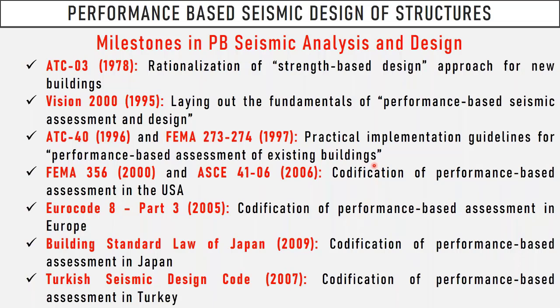As I mentioned, it started in the mid-1970s, ATC 3. It was the first time the strength-based design was introduced, and Vision 2000 laid the fundamentals of performance-based earthquake engineering. The ATC 40 project and FEMA 273 and 274 were the practical implementations, because you may have a good approach, you may have good ideas for design, or you may have a good theoretical basis, but it should be practice oriented.